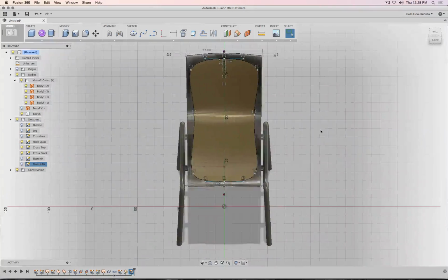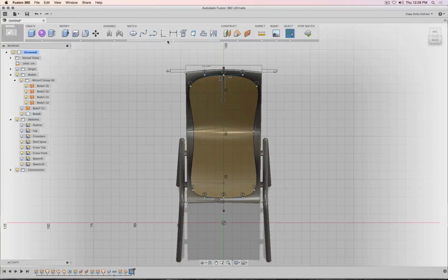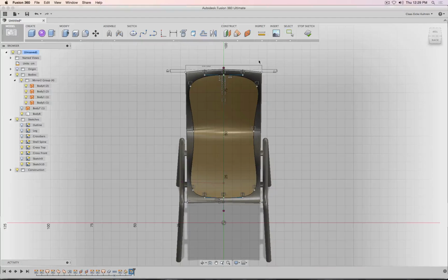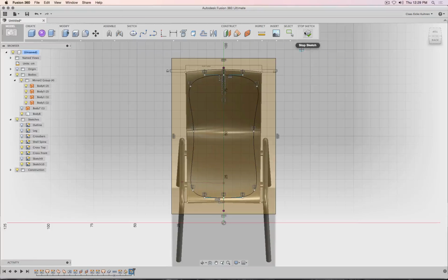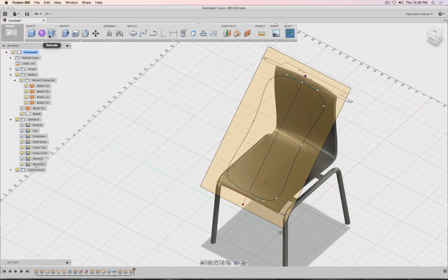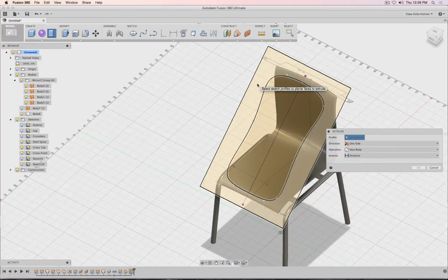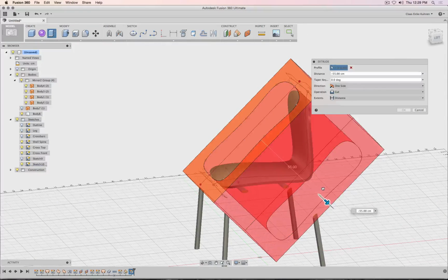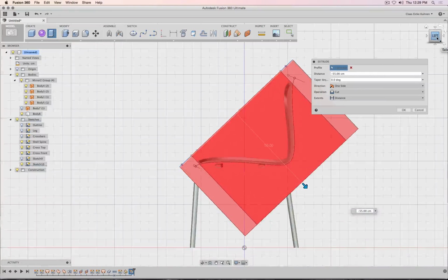What I'd rather do is actually a technique, the way how I work in Revit. I'm going to draw myself another really big rectangle. Rectangle there. So let's say from there down to here. Okay. Show the sketch, and then I say extrude. And you see now I can actually select the filling of my rectangle minus the surface of the shape I created first. And simply cut everything out, run it through completely.